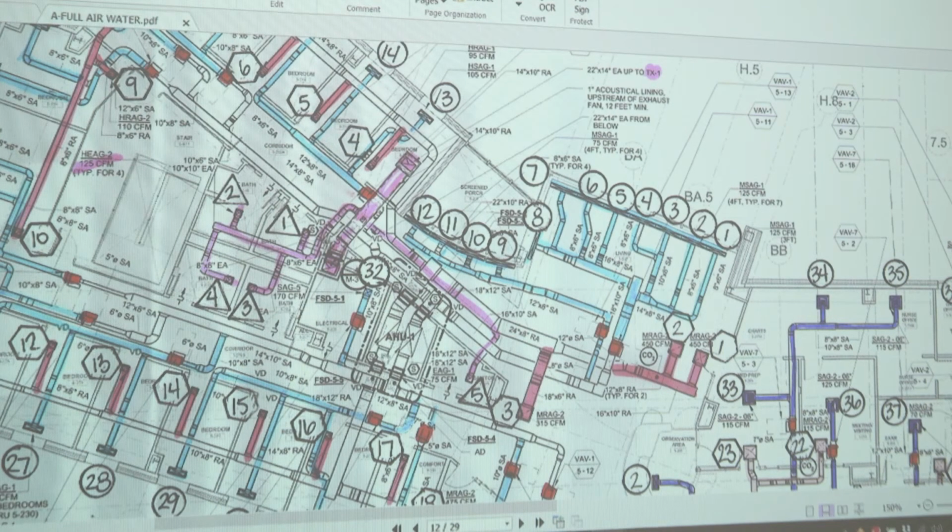Your air handling unit is sitting up here on the roof. The ductwork runs below the units, inside the dunnage enclosure, drops down into your shafts. Fire smoke dampers provide you your ratings at your shaft enclosure.